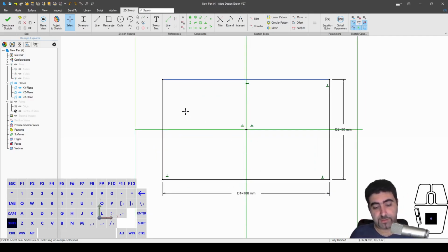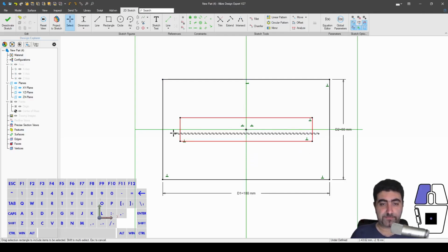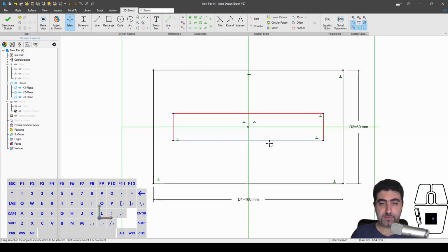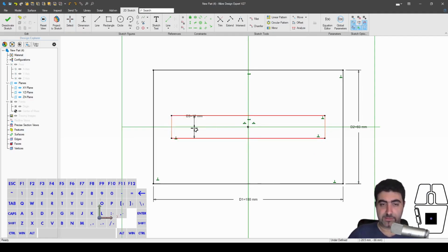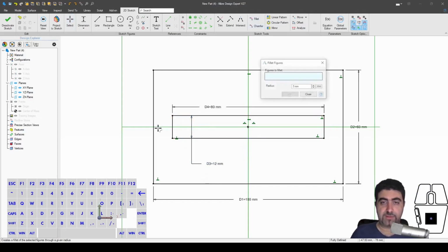And then what do I want then? Well, I need another, on the top surface, I will extrude this thing. Let's give it another horizontal here. I didn't auto-dimension it, right? So let's say 12 by 80, that's fine. And let's go make fillets.